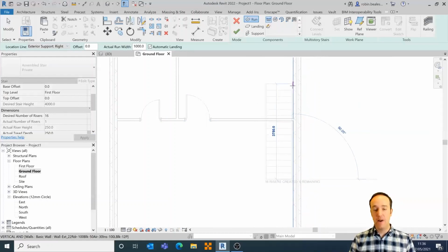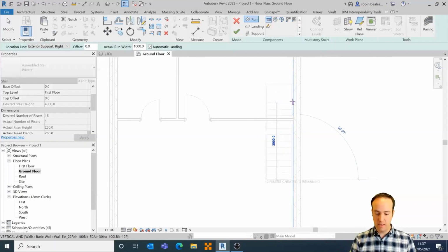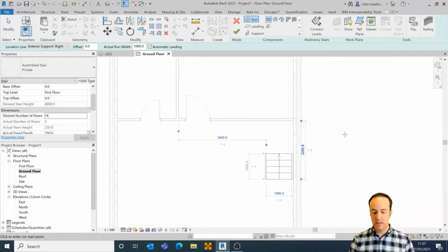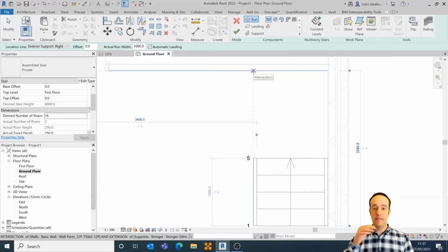So this is the complete length of the stair to get to where I wanted. I'm already a bit pushed for space in the kitchen, so I don't want to have any area where I can't have some full length cupboards. Nothing worse than having a cupboard or a kitchen that hasn't got the right cupboard space. So I want to go up a handful of steps and then turn 90 degrees and then go up the rest. So we want a typical L winder. So let's go up 5 risers, click my mouse, and then I'm going to leave a gap, and I'm going to make sure that I leave enough gap for the stairs to straighten up, turn the corner, the handrail turn the corner before it continues up the staircase.